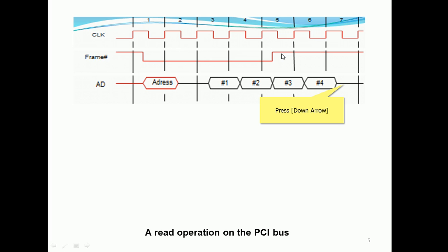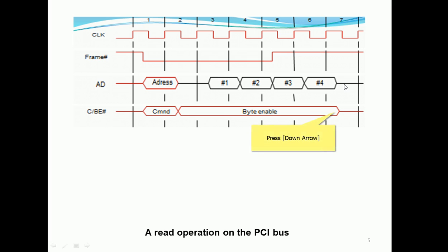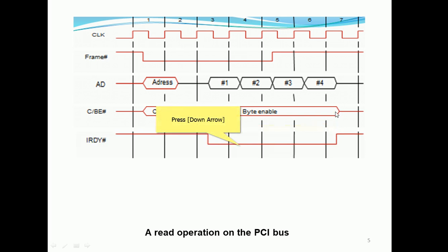It will be completely decoded and the complete address data is available. So that is the control, the connect command, and the byte enabling will be there. The command will be decoded and its complete meaning will be available at the half of the 2nd clock pulse, and the byte enable is ready from the 2nd clock pulse onwards, till it is available at the beginning of the 7th clock pulse.